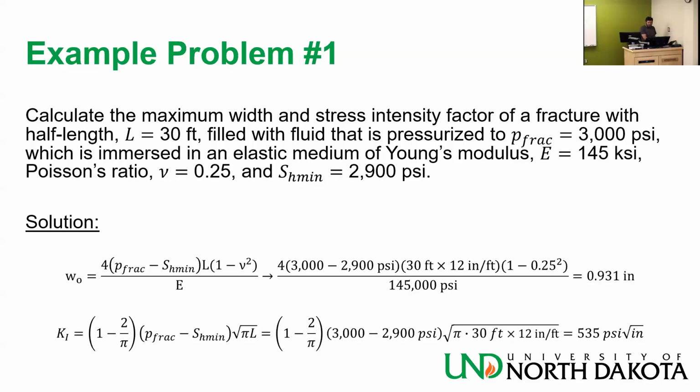Notice the weird units for the stress intensity factor and the critical stress intensity factor, or fracture toughness. That's basically the units that we are dealing with. It's very hard to get intuitive units. Many times we get MPa square root meter.